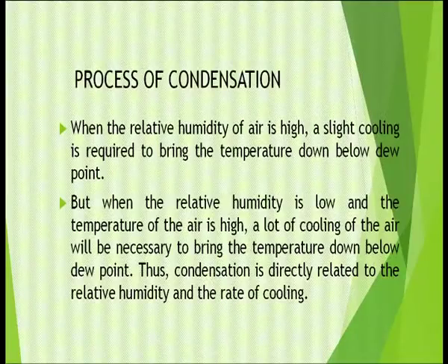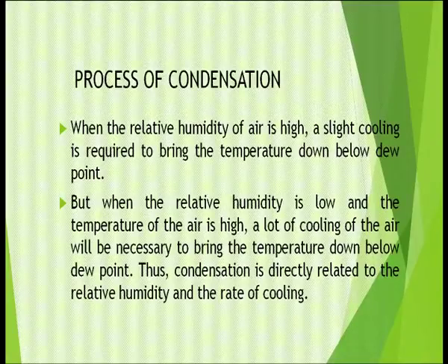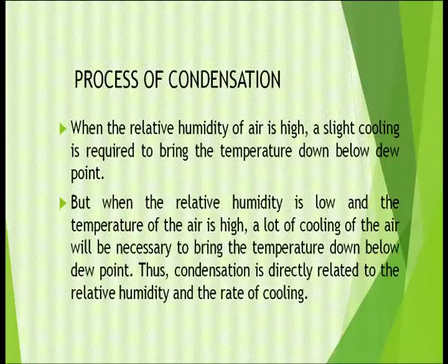When the relative humidity of air is high, a slight cooling is required to bring the temperature down below the dew point. But when the relative humidity is low and the temperature of the air is high, a lot of cooling of the air will be necessary to bring the temperature down below the dew point. This condensation is directly related to the relative humidity and the rate of cooling.